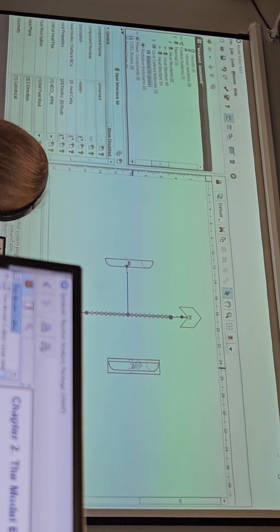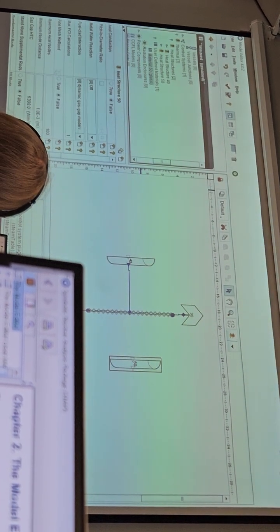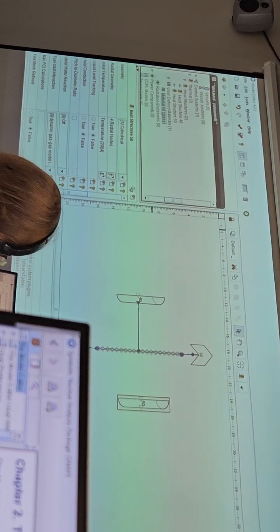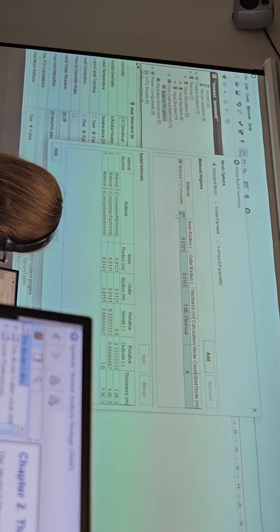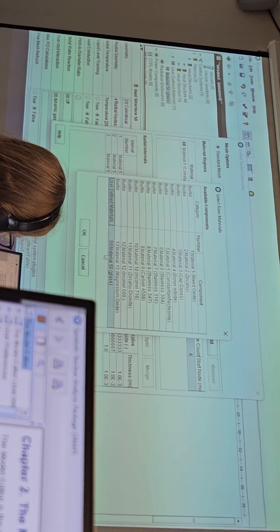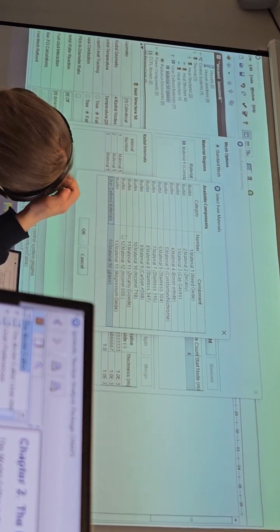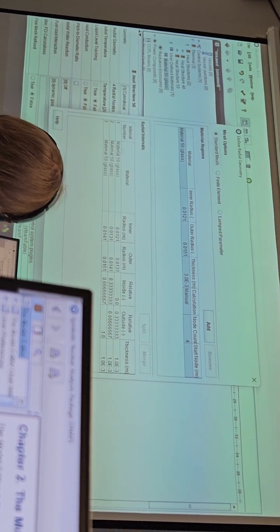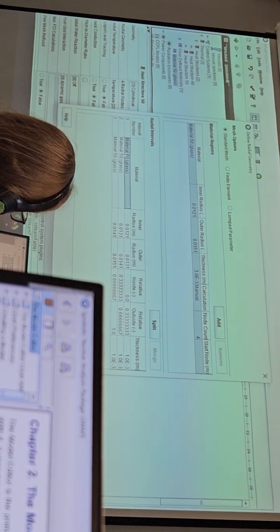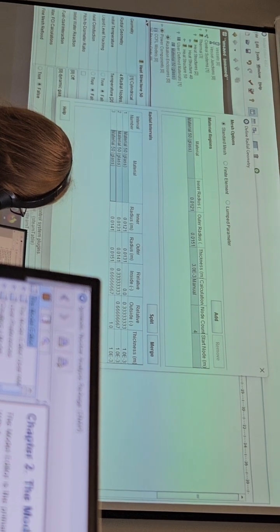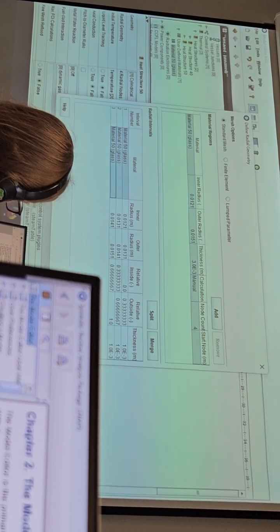Then we just need to click on our heat structure and go to the radial nodes, radial geometry. Here we can define our material. So now we have a user-defined material, glass. Just choose this material and press OK. It will define this material for all the radial nodes for our case. And then just press OK.